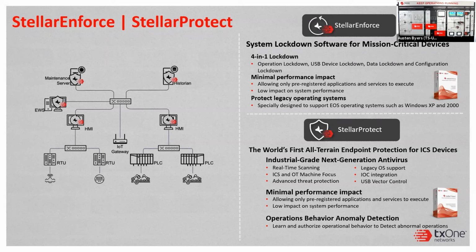With OT machines, there could be harmful commands that aren't necessarily malicious, like a simple stop command to a PLC can be detrimental, or adding excessive chemicals to the water supply like we saw in Florida. Those are harmful commands that aren't necessarily malicious that your IT security wouldn't be able to block. To prevent these types of attacks, we can do that in two different ways. We can either import the script files or the command files into Stellar. So if we see anything that deviates from those, we can be alerted to it or prevent those commands.